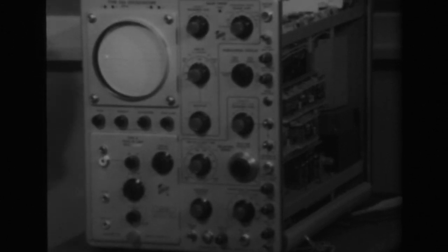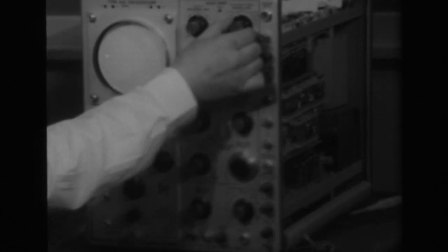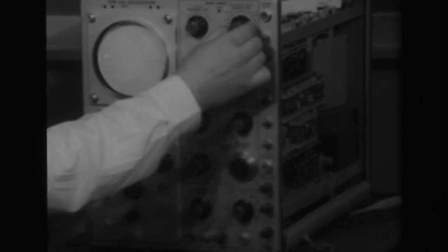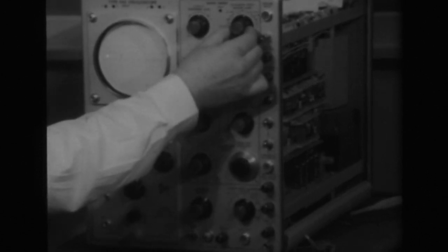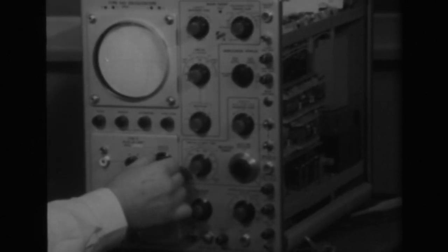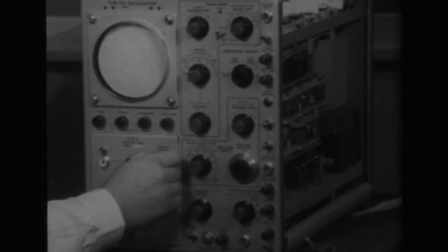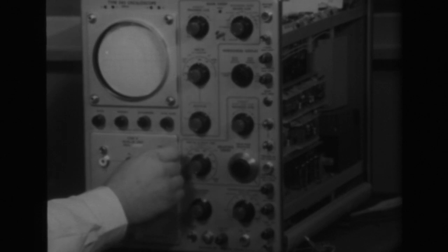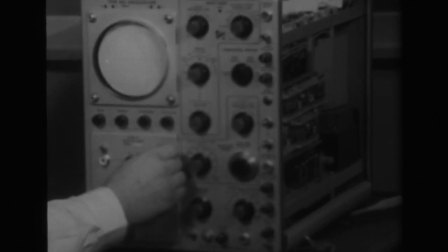Having completed the adjustment of the triggering level centering potentiometer, the next step is to verify adjustments so far. Set the triggering mode selector switch on internal plus or internal minus, makes no difference. Be sure you're in DC mode, and carefully turn the vertical position control slowly counterclockwise for negative internal until the sweep snaps one trace across the cathode ray tube. Note carefully that that occurs right at the horizontal center line.